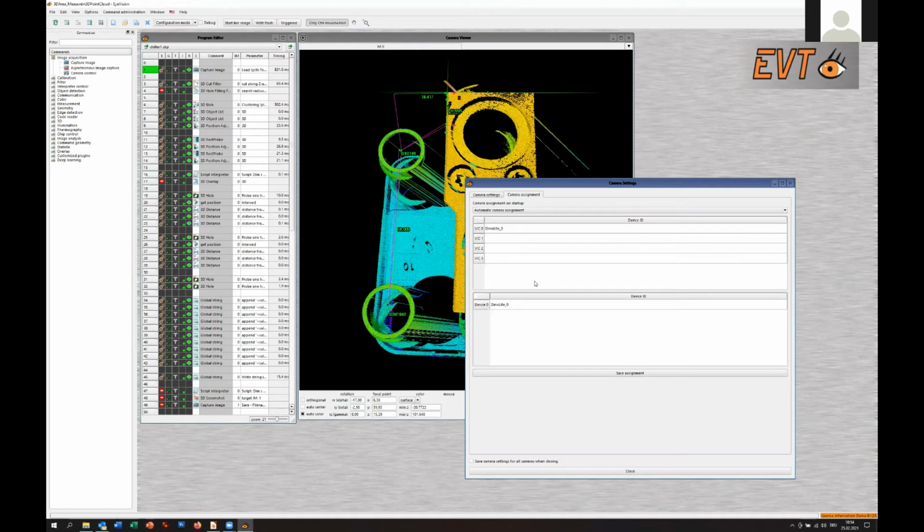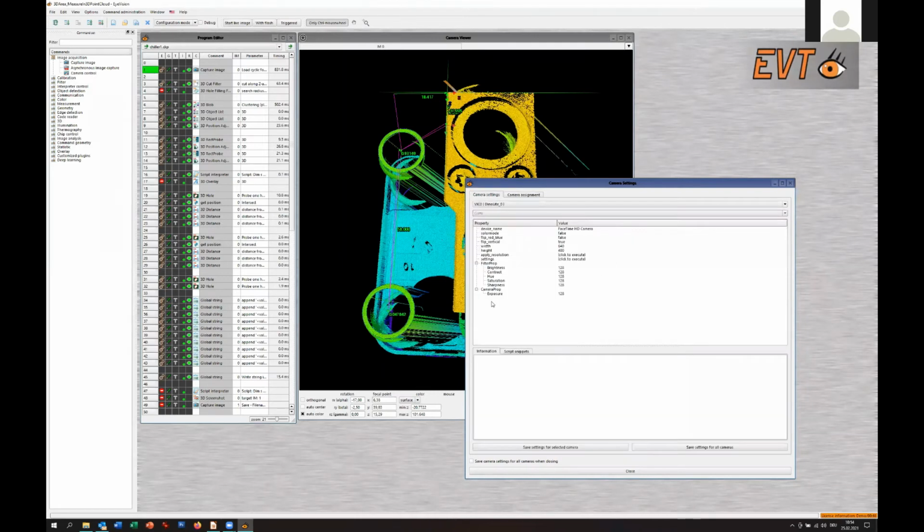And what is really important, that's why you have this menu. If you have multiple cameras, you can connect the device and the input channel to one line, so that if the system restarts, you always get the right image data in the right image memory. Or if one camera is not working, then you get a black image there and not a captured image, so you are sure. Of course, you get an error message, but you're sure you don't operate on wrong images. So this is a short intro to the camera settings. Please have a look at it, and later I come back to this.